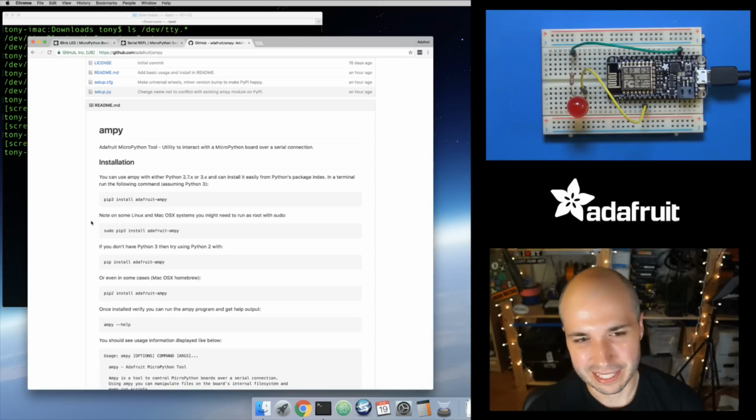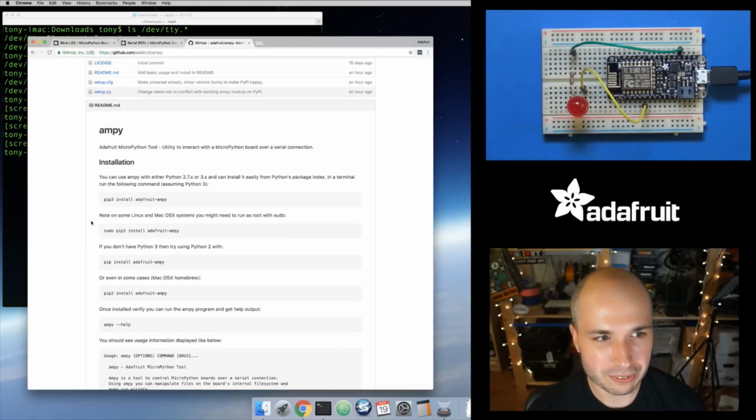If you wanted to put that into the flash memory of the Arduino, you've got to compile it in as a progmem thing, and it's not easy. Whereas with MicroPython, I really love how they've made the decision that everything has a file system, so you can write code that reads and writes files.